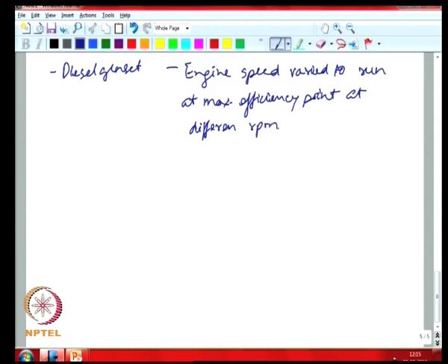So, such systems are also used in hybrid vehicles, etc., where your genset, your actual IC engine might operate at the maximum efficiency point, and the additional torque required might be provided by an electric motor over and above your average torque level that needs to be produced. So, that way you can operate your combustion engine at its best efficiency point, giving you lower fuel consumption. Okay. So, similar principle applies to vehicles also.